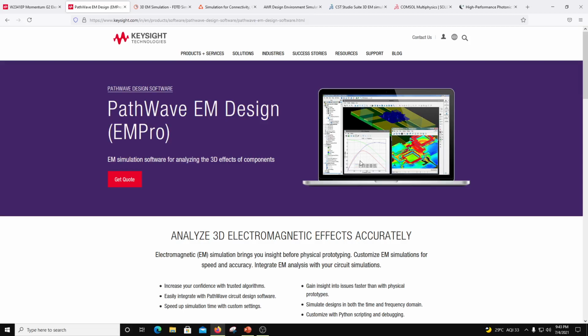Now in FDTD, the cell is a cube, right? Once the cell is a cube and everything is defined on the edges of the cube, as soon as you take a diagonal distance between two vertices in a cube, there is going to be a dispersion. That dispersion is an error, and it has to be bound within a certain maximum dispersion which you are going to see along the diagonal. That is governed by the Courant factor S, which should be less than 1, right? So dispersion in FDTD grids is more important.